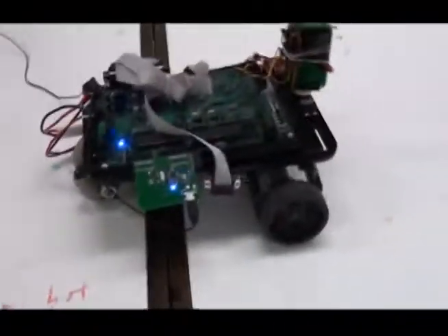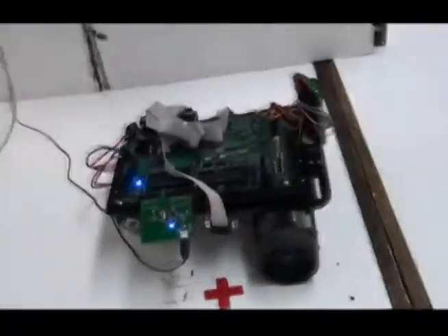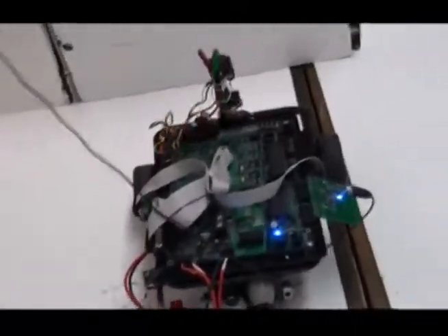After getting to the final location, our robot switches to the return map. Pretty much the task was that the obstacles could change, or the path could change, or the path just may not be the most fit path to return to the starting location, and thus it'll reset to a return map, which then sweeps and updates the entire map around it, and it would go back. The return function took slightly longer, a 14-minute time, but it was very effective in mapping the entire map, as well as avoiding all the obstacles and reaching the destination.